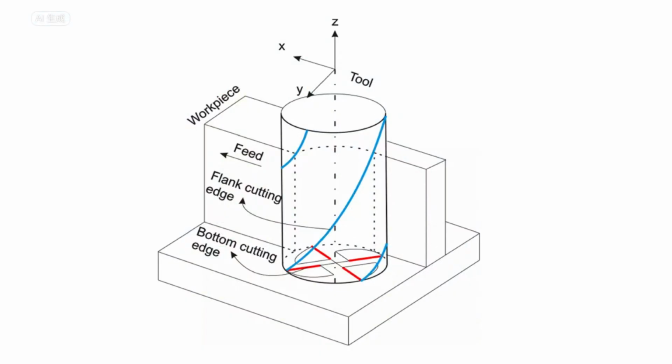How end mills work. A specialized end milling machine or regular CNC machine accommodates suitable end milling tools in its spindle or other rotating components. Then, it controls the movement precisely across the workpiece in XYZ axes. The tool path, the size of the cut, depth, speed, cycle time, and all other variables depend on CNC inputs and geometry and end mill sizes. The detailed steps for how the end mill works.